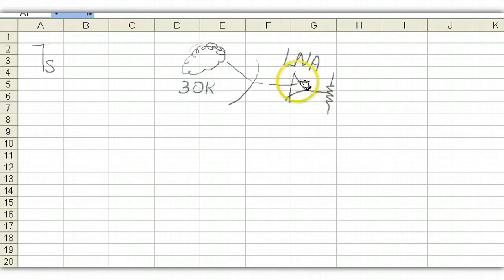All right, now let's talk about this amplifier. All amplifiers make noise, and we characterize this noise as the equivalent temperature. So when you buy an amplifier or you design an amplifier, the two things that you design into this thing is the gain of the amplifier and how much noise it generates. And we can characterize that noise by an equivalent temperature. And typically a pretty good low noise amplifier at this frequency has a noise temperature of about 100 degrees Kelvin.